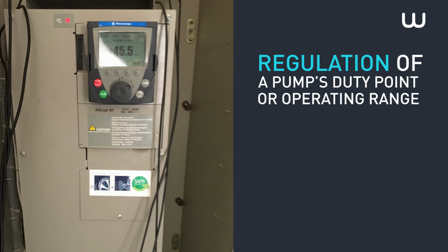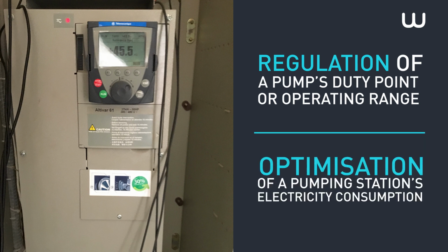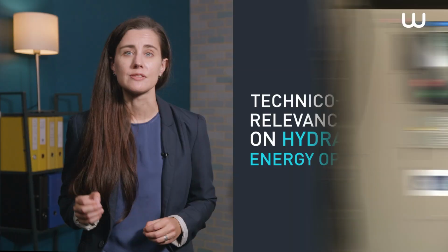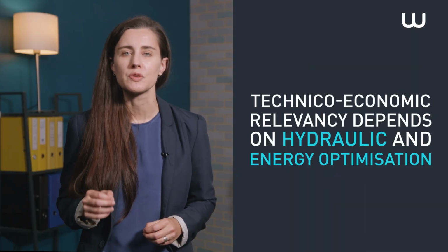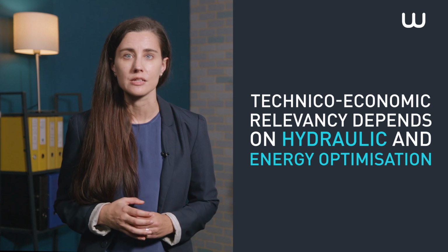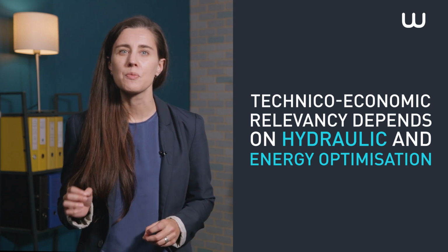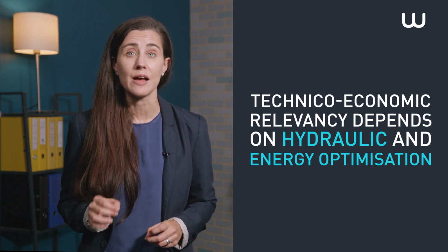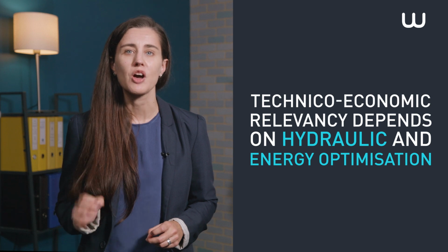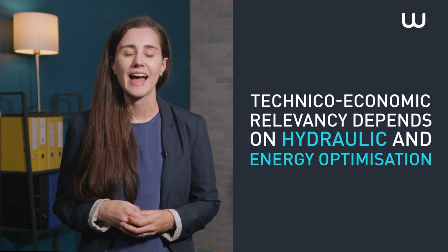Fitting a variable frequency drive enables the duty point or operating range of pumps to be regulated with the help of an electronic device in order to optimize a pumping station's energy consumption. The technico-economic relevancy of fitting a variable frequency drive must always be studied in order to check that it enables pumping to a network located downstream of the station to be optimized in terms of water and energy.